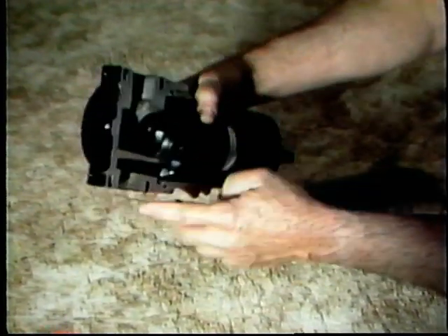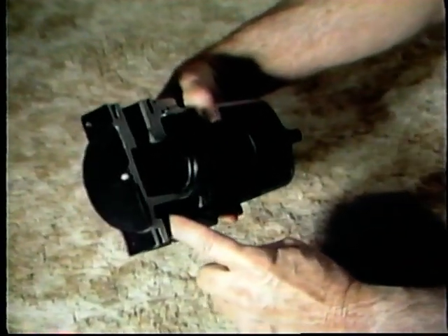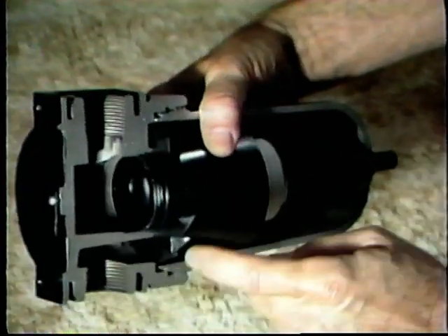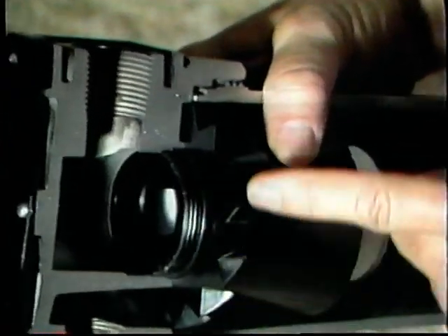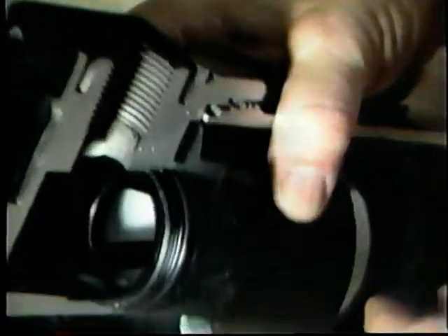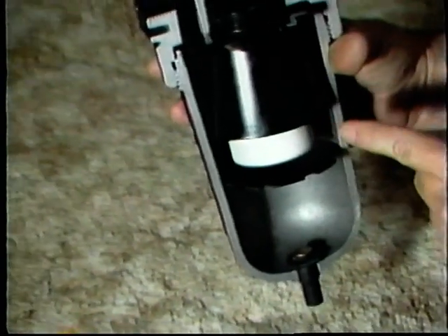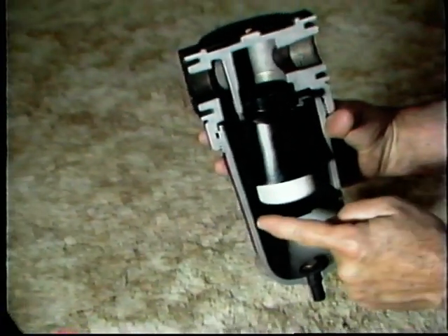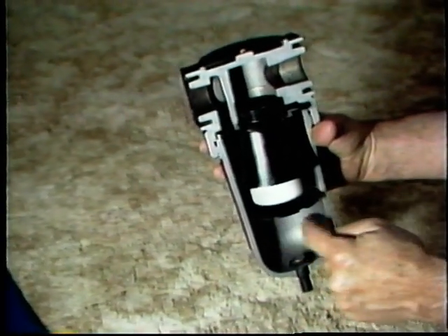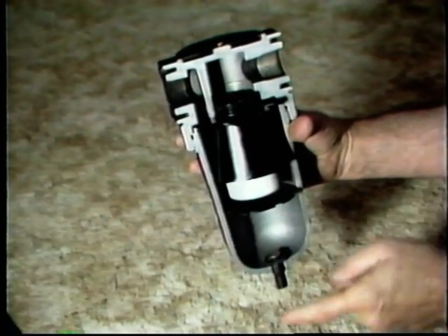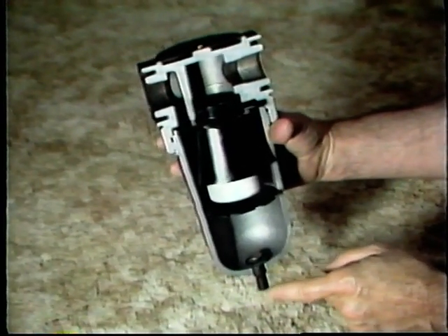The inlet directs the incoming air through the openings in the deflector plate. This causes a swirling action that throws the larger impurities and condensation out by centrifugal action. They collect on the sides of the bowl and run down past this baffle here into this quiet chamber where they can be drained off through the bowl drain.